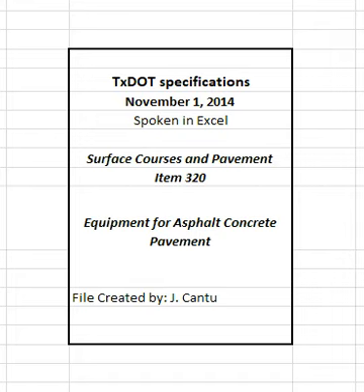2.1.3 Modified weigh batch plants. Provide a mixing plant that complies with Section 320.2.1.2, weigh batch plants, except as specifically described below. 2.1.3.1 Aggregate feeds. Aggregate control is required at the cold feeds. Hot bin screens are not required.